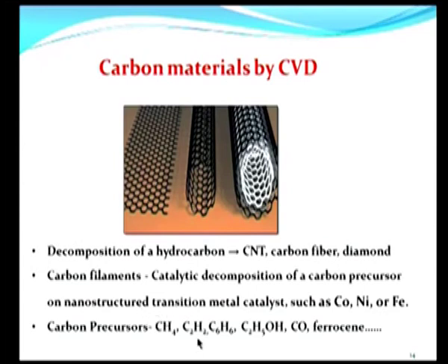That is, it is possible to employ methane, acetylene, benzene, ethyl alcohol, carbon monoxide, ferrocene and so on, a whole variety of carbon containing vaporous compounds, and then by slightly altering the methodology for decomposition and catalysis of these into carbon nanotubes, it is possible to get multi wall, single walled and so forth by the general CVD method, which works at around 700 to 800 degrees Celsius.